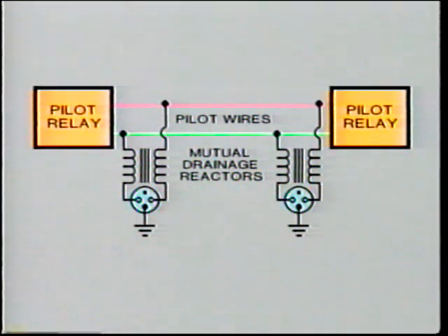On pilot wire protection circuits, the protector is normally located at each end of the telephone line or other remote drainage locations. Drainage reactors can be obtained with continuous drainage ratings up to 50 amps, and for applications where transient line voltages could be as high as 20,000 volts.